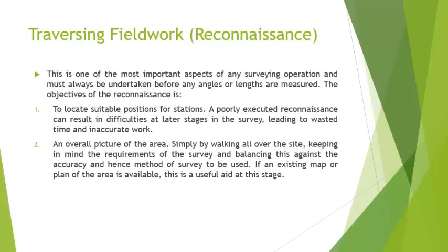Start with the reconnaissance. This is the process where the surveyor's team go to the working site and get the overall picture of the area. This is where the suitable positions of survey stations are located or selected. The conditions of the site are determined and sometimes sketched or pictures are taken. Some surveyors also bring very light equipment such as the prismatic compass just to get a rough idea on whether the boundary marks or any reference marks are in good condition or otherwise.